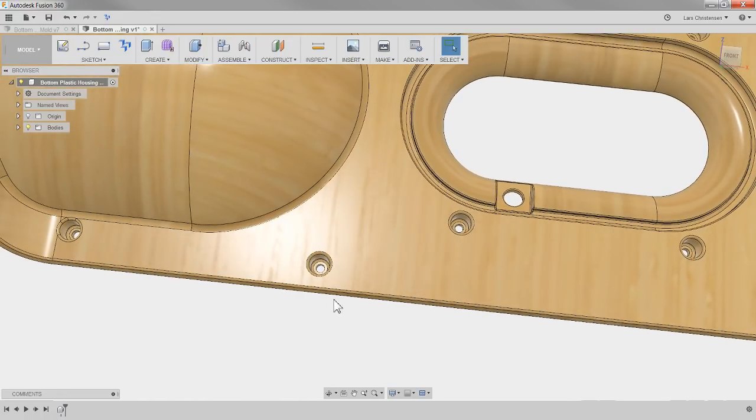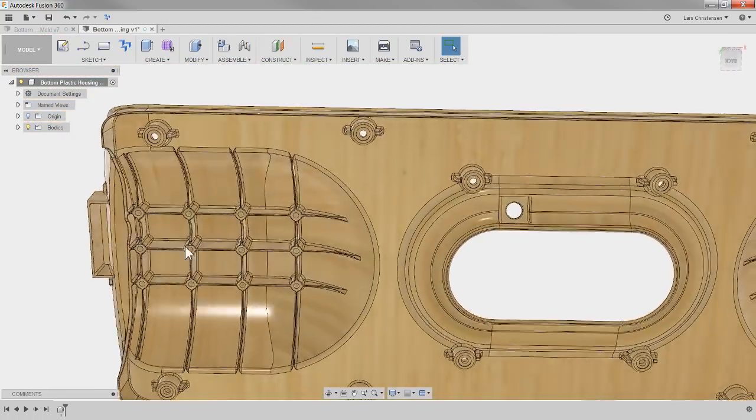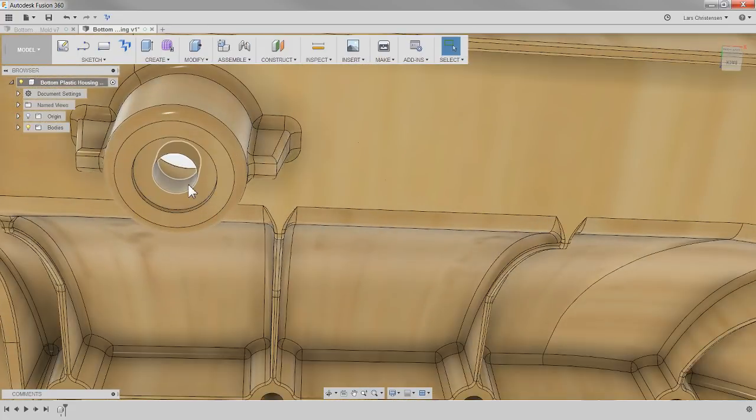Now, we could start creating single surfaces to block these holes off. But because it's pretty obvious to me what this is, I can make my life easier by actually eliminating the holes in this core for this first step. The way I'm going to do that is I'm just going to select the inside of the face here and hit the delete key on my keyboard.